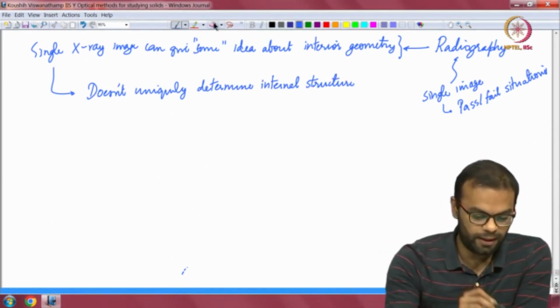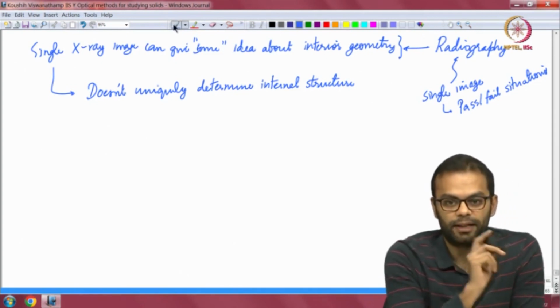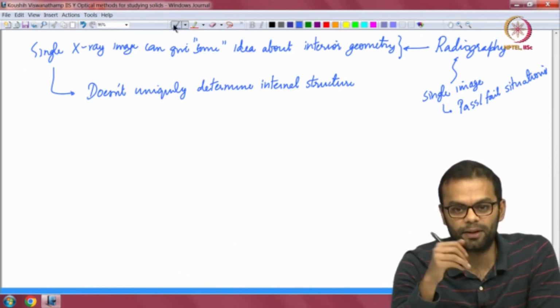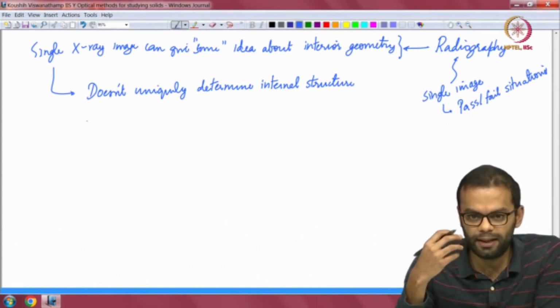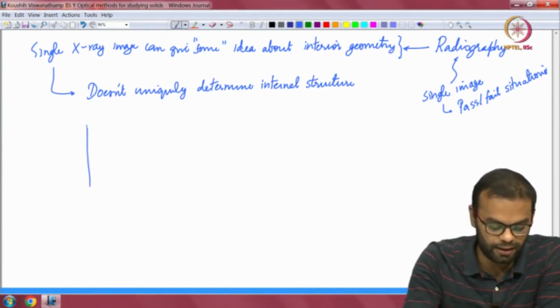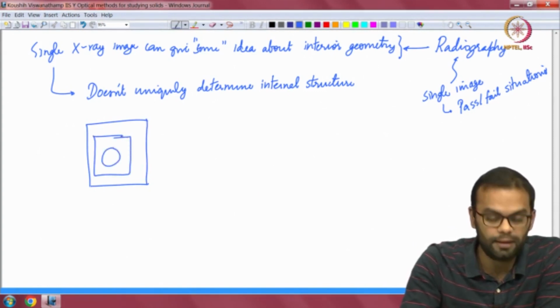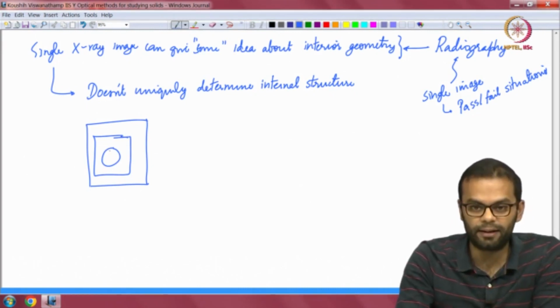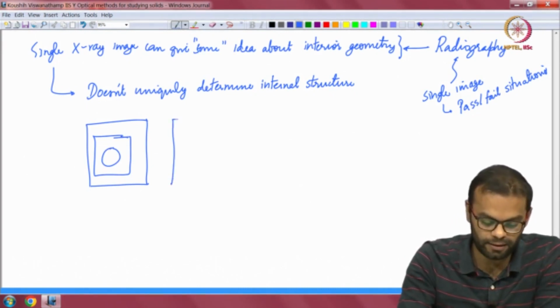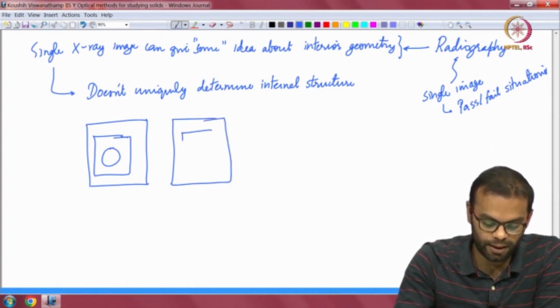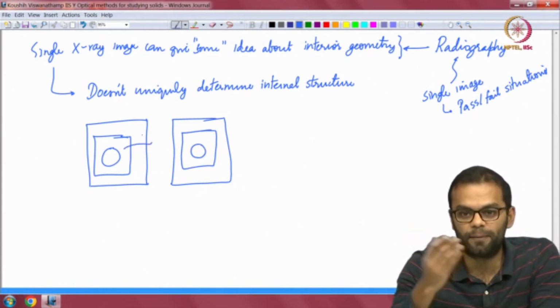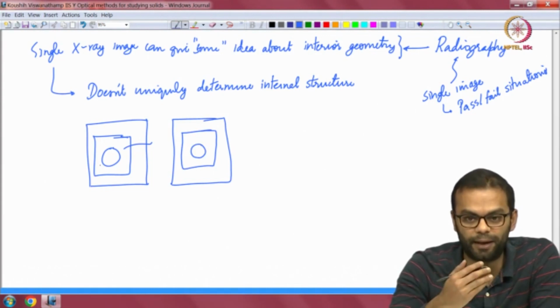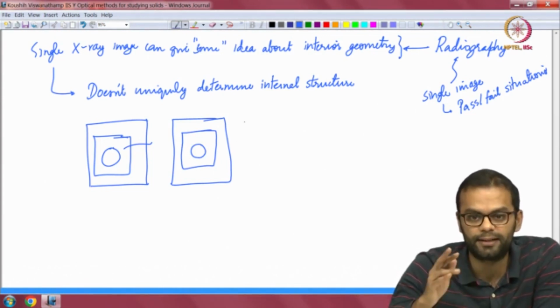Okay. A very simple way to look at this is basically to say, if the metal's absorbance was very high, okay, let us say you are passing X-rays through lead or something which has very high absorbance, then the intensity gradation in the spherical cavity image, remember this was our screen, this was our image, and then you had this, the intensity gradation you will get here will be very similar to the intensity gradation you get here for the cylinder case, because this guy is so completely dark compared to this is completely bright in comparison, and likewise over here, and so the intensities will start matching.